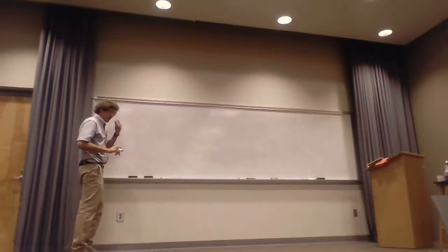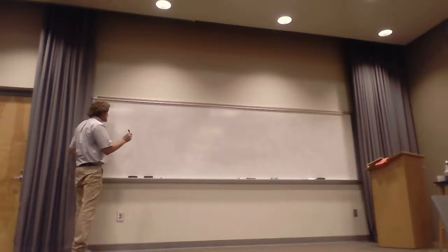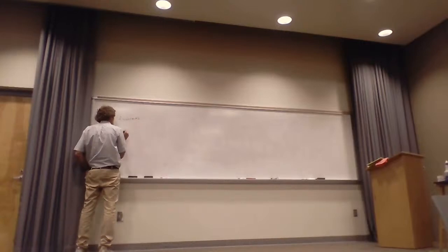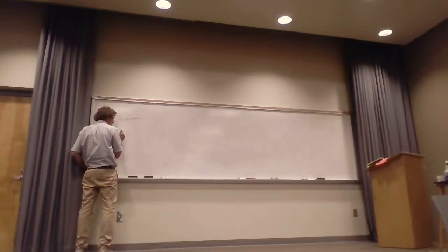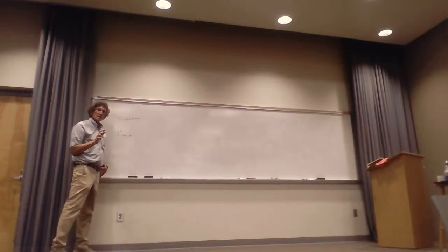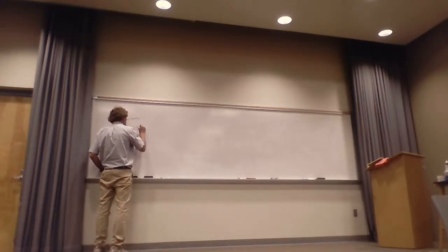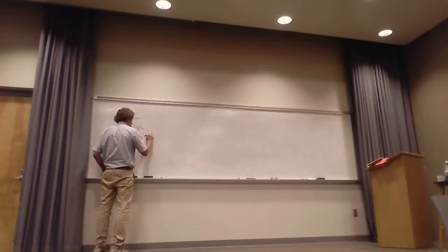So give me the problem. The frequency is 600 megahertz. It's a planar wave propagating in the z direction. It's going to strike a material of Teflon. Relative permittivity is 2.1. Permeability is 1. And the E field is 1 volt per meter in the Y direction.